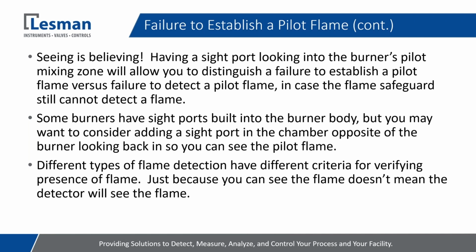Also, the different types of flame detection, some are more or less sensitive to pilot flames, and so you may need to make adjustments accordingly. I just got done with a startup where we switched from UV scanners to flame rods, and we needed to make some pilot adjustments because the flame rods weren't... We could see the flame, but the flame rods couldn't pick it up, so we had to make adjustments to our pilot gas pressure so that the flame rods could detect the flame.